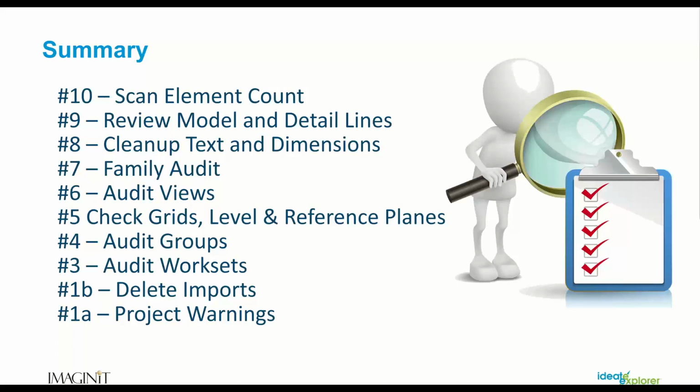Same look and feel that we can verify that maybe somebody again copy and pasted those into the project, same name but different look and feel. Remember, family auditing, we want to do that. We want to make sure that we vet out our families, and this is a great way of looking in and deepening into that particular family. Again, for the views, I'm going to go back with that reference plane one, that we can get rid of those non-named reference planes, and groups, making sure that we manage our groups appropriately. And of course, my top three, working with worksets and moving things to a proper workset, get rid of those imported details that we don't need, and managing our warnings.